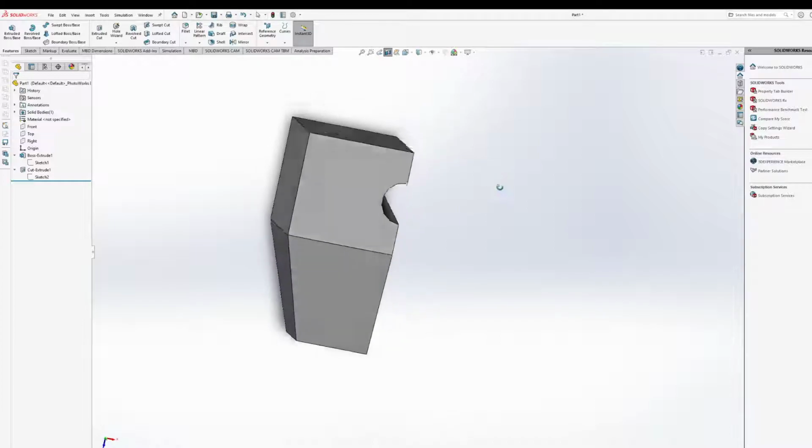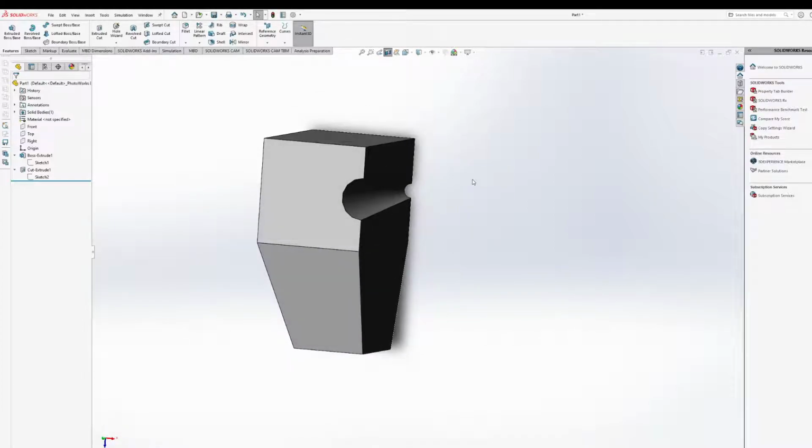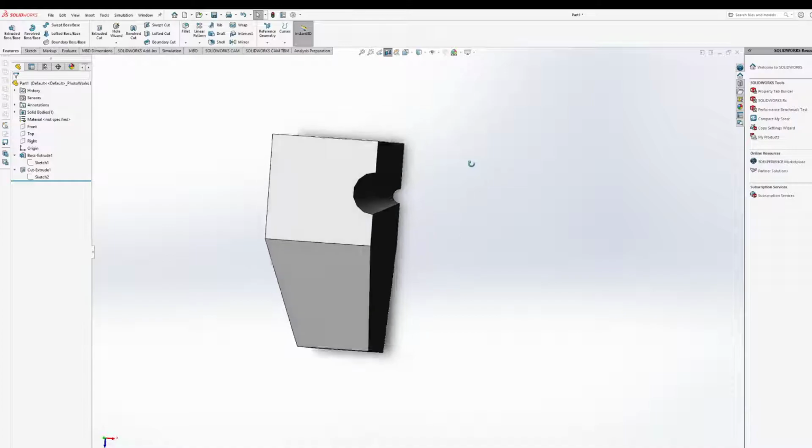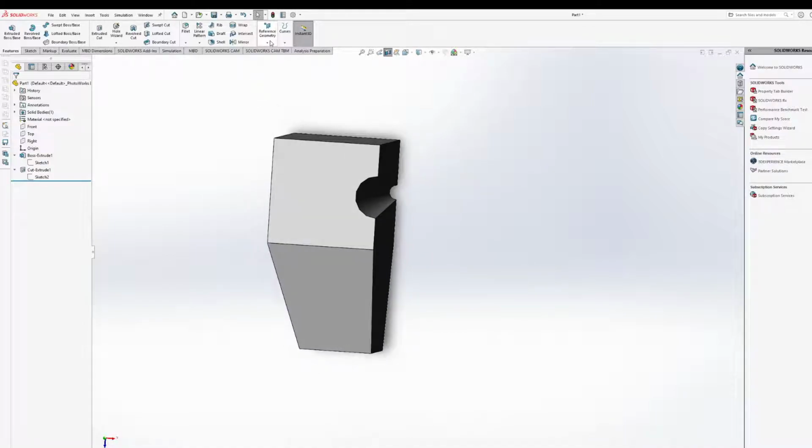Usually, I would say you're going to want to stick to one plane until you make some form of an extrusion. And then beyond that, you can start sketching on either of those other indicated planes. You can create other planes to work on other than the front, top, and right, as well as plenty other geometry types as well. So one nice thing, and we'll start getting into this a bit more later, is that we have a reference geometry section.